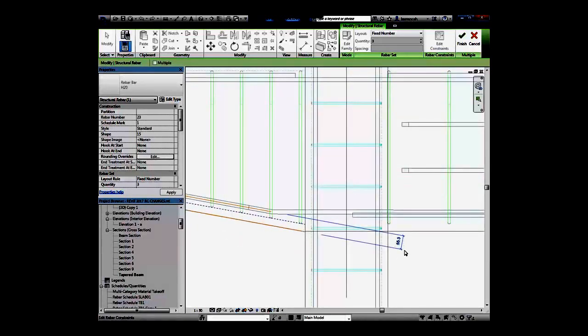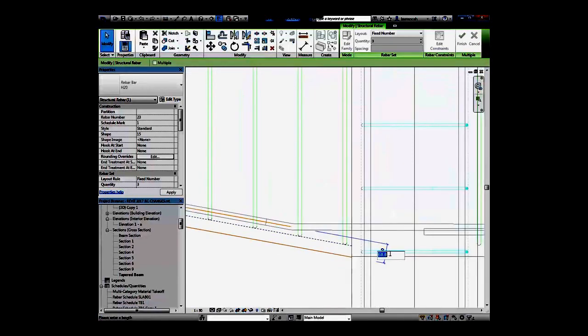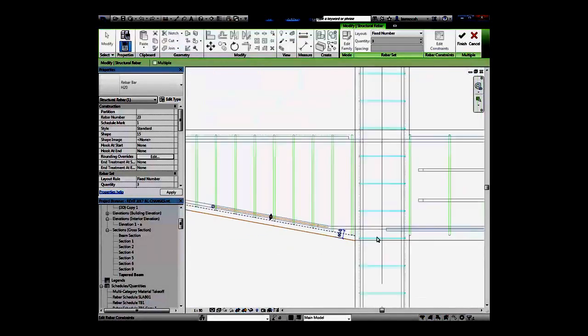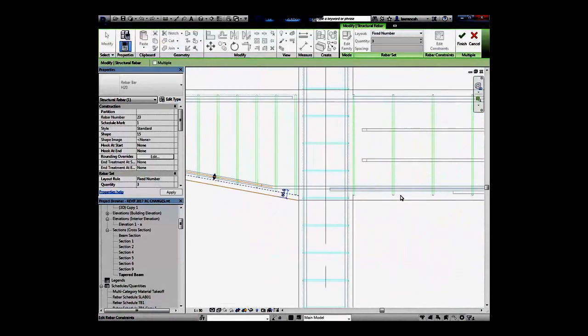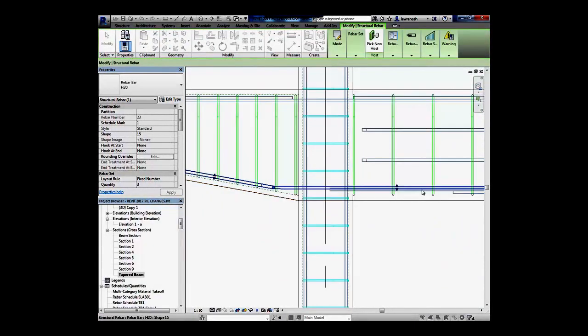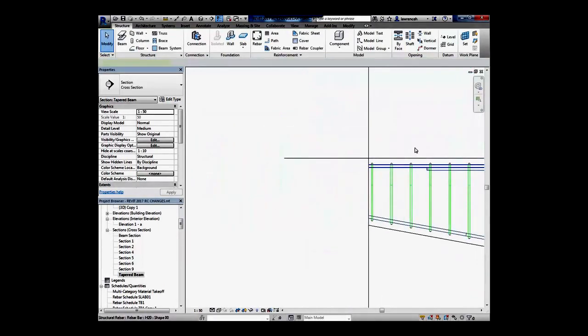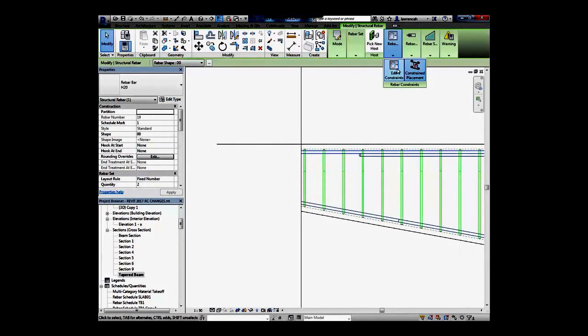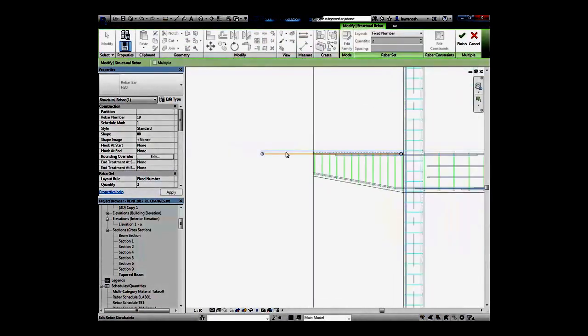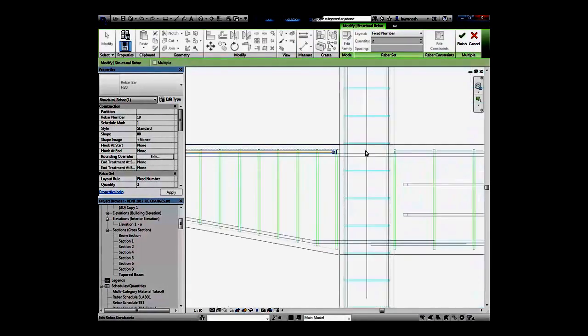and you can see it has a very simple dimension in here, and we can just type in the constraint we're after. So in this case it might be 60, and you can see it very simply moves that bar. When we're done, if we want to finish, we just hit the green tick and that's now done. Obviously there you can move across to any other bar and edit those constraints and then see the relative dimensions attached to it.